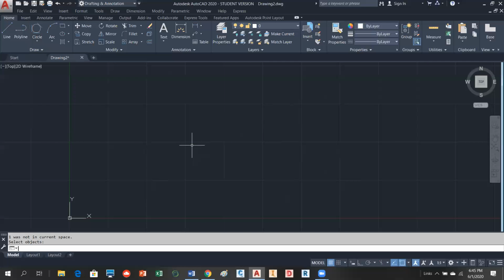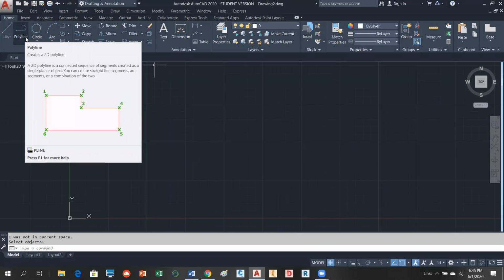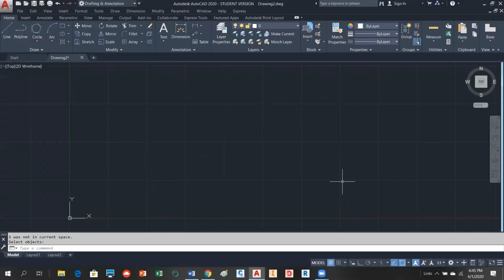All right, we're gonna take a look at the rectangle command. So this command actually generates what's called a polyline, okay? So it actually generates this kind of object right here, a polyline, and it'll create what's called a 2D polyline. So what we'll notice when we do this is that this object isn't really a rectangle. It's actually a polyline, but it'll have 4 objects associated with it, or it might have more than that, depending on how you draw it, but they'll all be one object, okay?